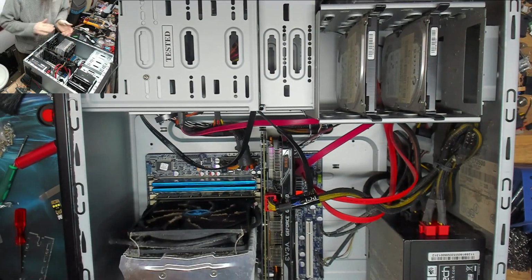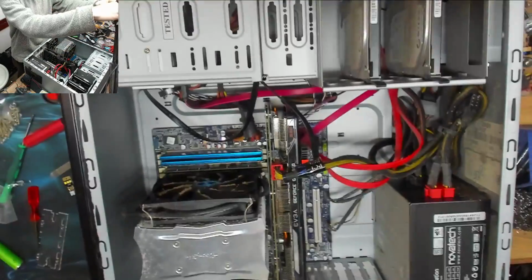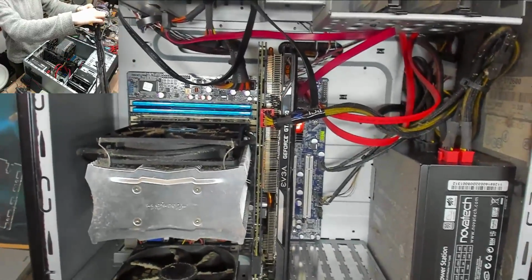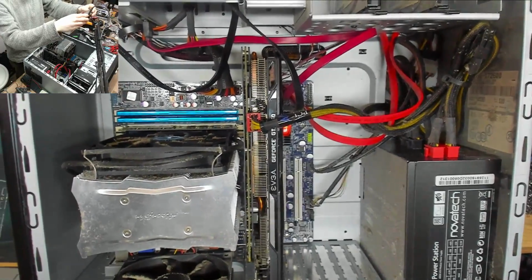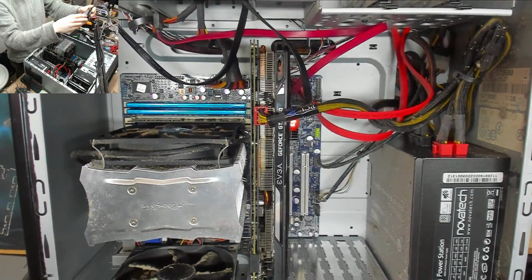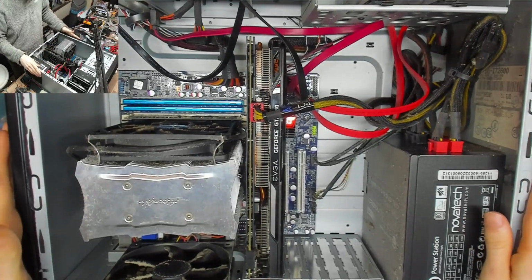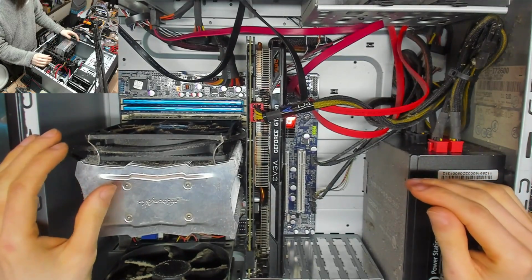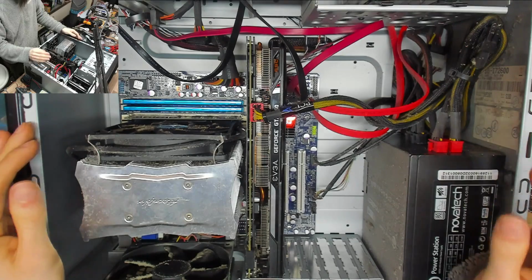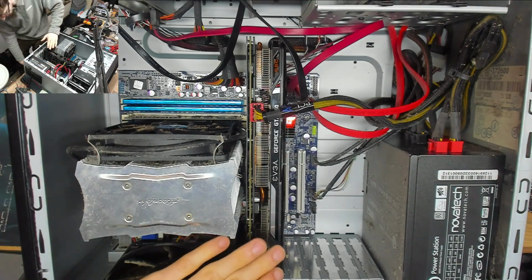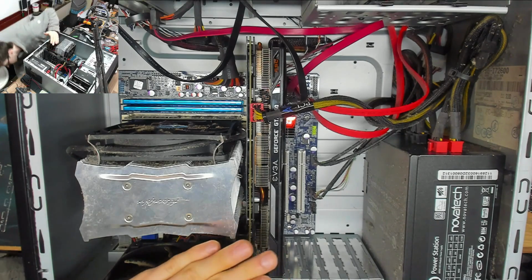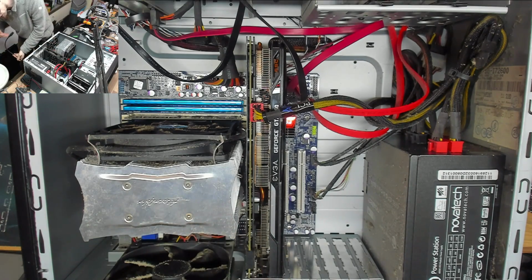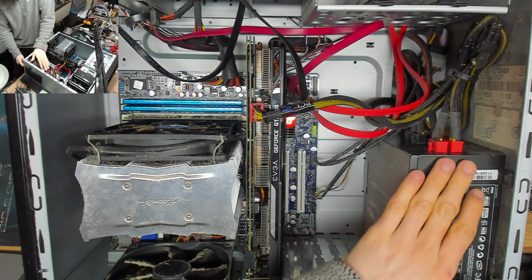So the first thing we need to do is reproduce the fault. What I'm going to do first is start it up and start running some stress tests, and we're going to see if we can trigger the fault to occur. Because when you have an intermittent fault, just waiting for the fault to occur can make diagnostics very long and tiresome. So if we can find a specific stress test that will cause it to crash or error or otherwise just show us problems, that will make testing much, much faster because we know what we're looking for then.